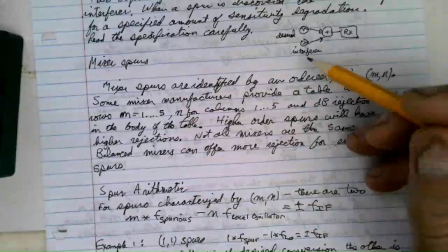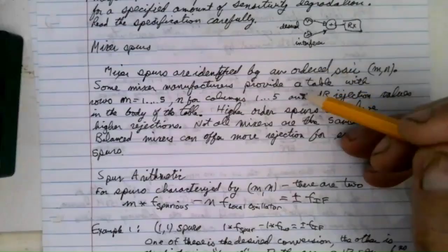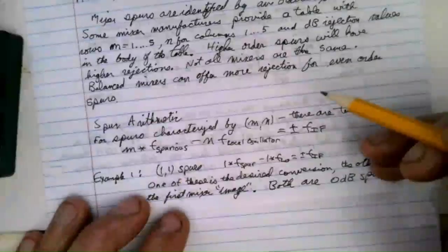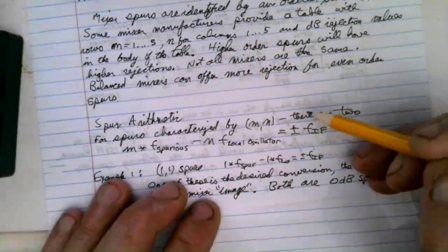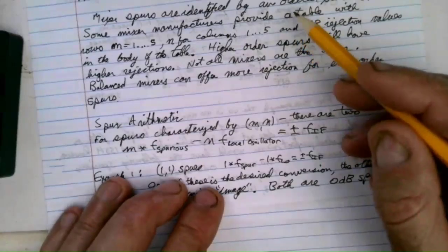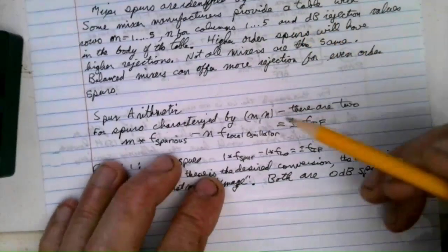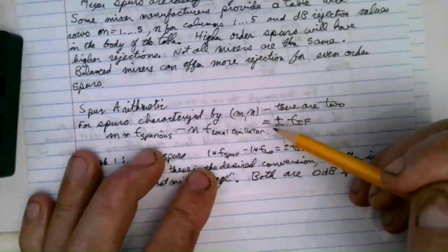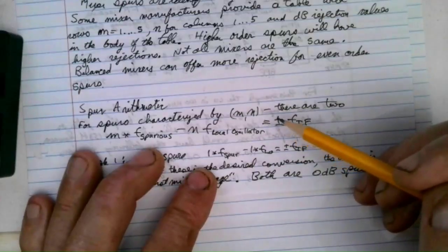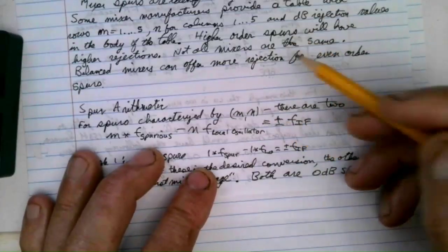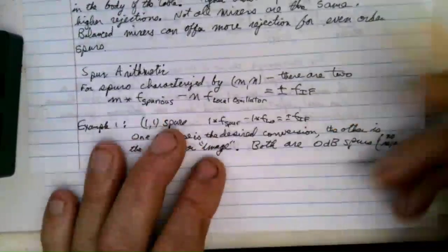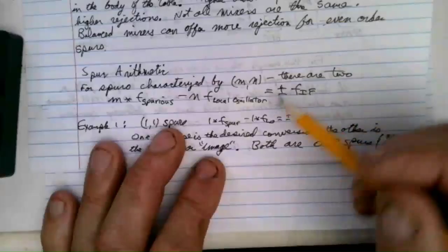And so the question is, what's the manufacturer willing to guarantee? That's your job as designer, to pay attention to what the mixer is specified to do. And for intercept point, conversion loss or conversion gain, noise figure, all of the metrics for a mixer, when you choose a mixer, you're paying attention to that in the data sheet. Now, you may make your own mixer, or you may buy one, and that's your choice.